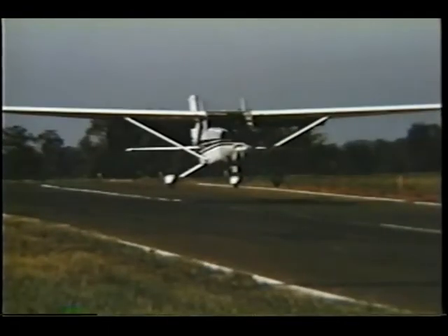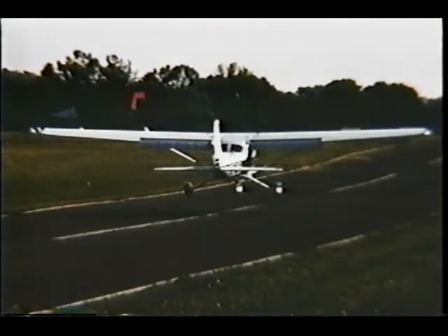Now, how many of you are aware that landing at less than the maximum landing weight can also result in your landing long? Well, it can. And it will. As you'll recall, a little earlier in this program, we said that if you don't have a published approach speed, you should carry 1.3 VSO on short final. Well, that's true, but it's vital that you understand the definition of VSO in order to avoid landing long.